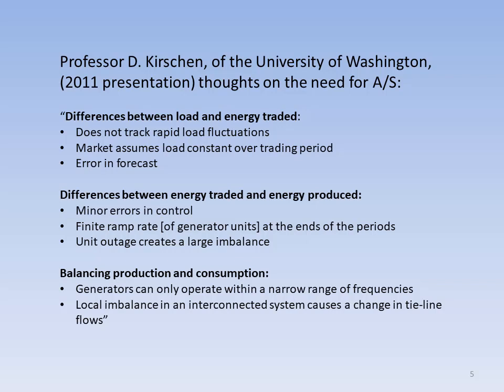Additionally, every generation plant has its own physical limitations. It has a maximum and minimum ramp rate in megawatts per minute. Supply and demand must balance across the entire Western Interconnection. Excesses or deficits in one balancing area produce changes in tie-line flows with neighboring balancing areas.